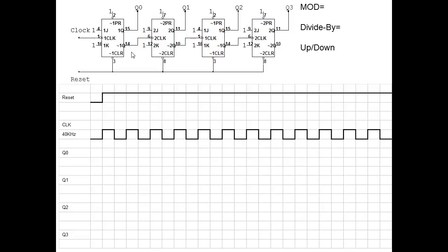You're drawing Q0, right? You're drawing off Q, but you're clocking off of Q naught. So we draw one, clock off the opposite of it. So what we see down here is going to be the opposite of what's actually feeding the clock of the next one. So let's go through and figure out how this is going to work.